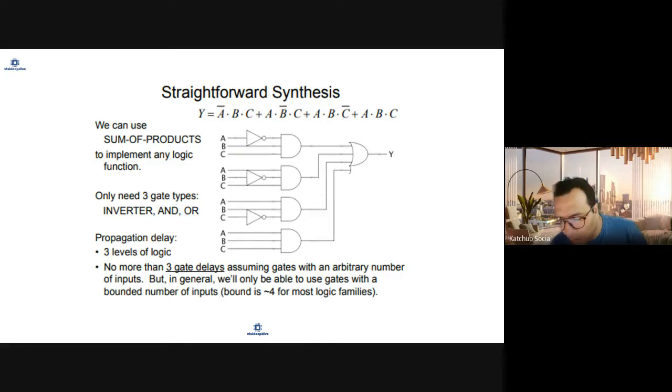I'm taking a hypothetical example, that this is your sum of product form. So a or b, whatever that condition is, it can implement that logic. Now these are technology independent logic. What Jayesh asked is basically about standard gates, which are GTech gates, not technology specific. So these are not of different drive strength or different delays as provided by your library files. Right now these are just standard general AND gates and OR gates. So if you think simply, it can convert this sum of product equation into gates.